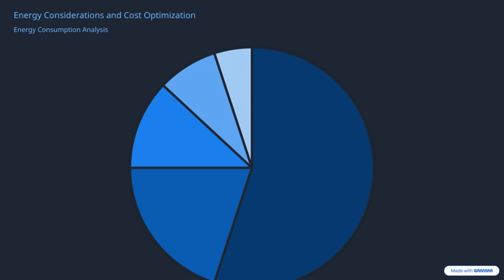Membrane bioreactors and hybrid systems, like moving bed biofilm reactors, are also promising options for better performance and lower energy footprints. Equipment efficiency is another critical factor. Modern technologies, such as turbo blowers versus traditional positive displacement blowers, high-efficiency motors, and smart control valves, provide long-term operational savings. Additionally, recovering heat from blower cooling systems, or employing energy-efficient mixing equipment can further optimize energy use.